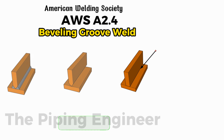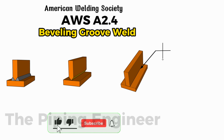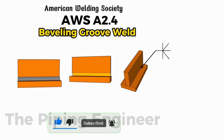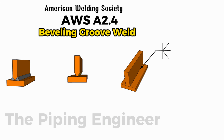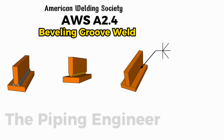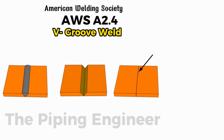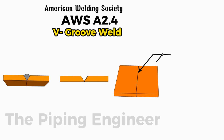On both sides of the reference line, if the beveling groove weld symbols appear on both sides of the reference line, it indicates that symmetrical beveling and welding are required on both sides of the joint to ensure complete joint penetration. Let's explore another common type of groove weld symbol, the V-groove weld. Here is how the rules apply to a V-groove weld.